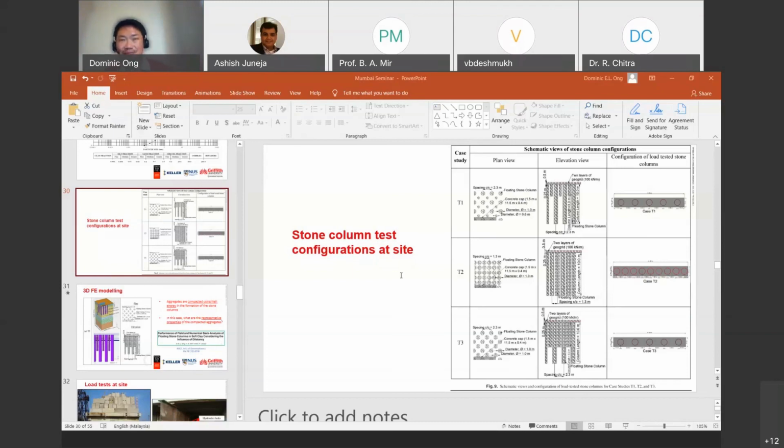and then after that we move on to having a well-graded material, which means smaller size as well as medium-sized particles in contact. Obviously, the contact points are more, and of course, when you have more contact points, it actually gives you greater strength parameters. So that is the influence in terms of the particle gradation in terms of your soil strength. So for uniform sand, because all your particles are the same size, the point of contact is going to be much lesser than if you have a well-graded sand, for example.